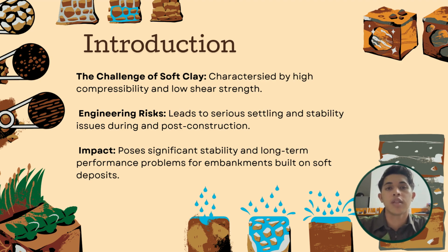As we look at the introduction slide, the root of our engineering challenge begins with the soft clay itself. Geotechnically, these soft soil deposits are highly problematic because they are characterized by high compressibility and low shear strength. Because the soil has very little capacity to support heavy load, it introduces several engineering risks. Specifically, it leads to serious settlement or differential settlement and a major stability issue both during the active construction phase and in the long-term post-construction period.